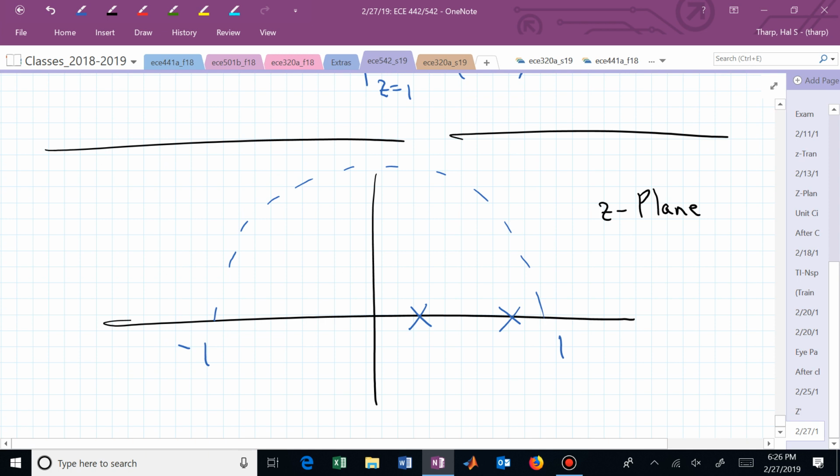Which of those poles is the dominant pole? And when I say dominant, is that the fast or the slow pole? If you're having trouble, I would just insert some generic numbers. I would say, oh, that one on the right is at 3/4 and the other one's maybe at 1/4, just to give us something to think about.